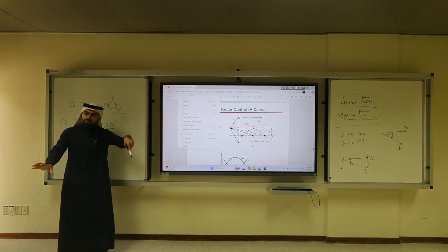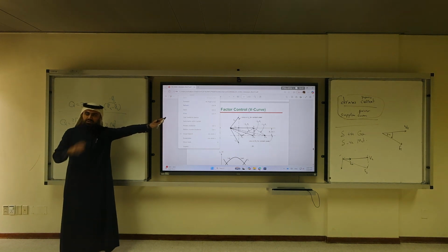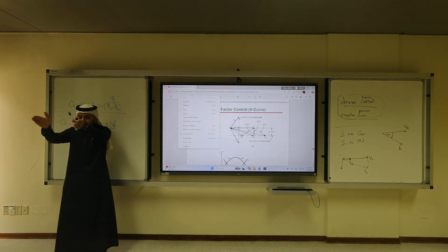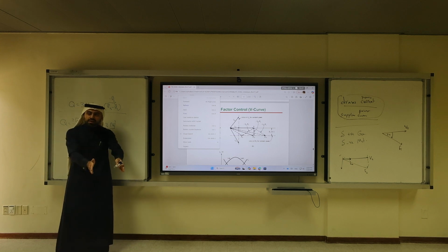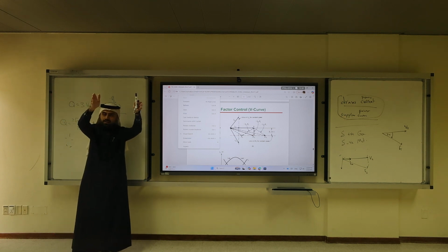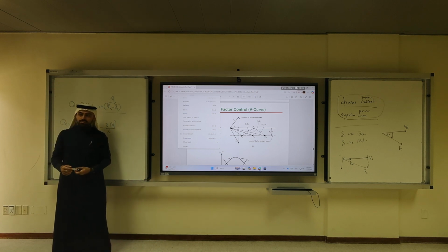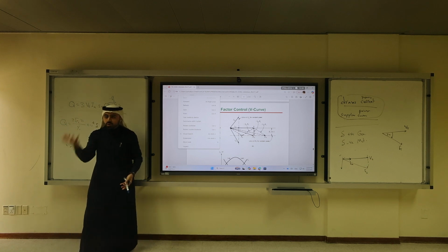If your output by the EV is something that mechanical engineers are doing, you can pick a smaller electric motor, but you should pick a bigger gearbox. Or you can pick a bigger electric motor and a smaller gearbox. You should co-optimize the two designs, not only your motor. Get it? Yes. So your gearbox would have losses. With the more expensive ones with complicated designs, worm drive, strange shapes, whatever, you can pick an even smaller motor.